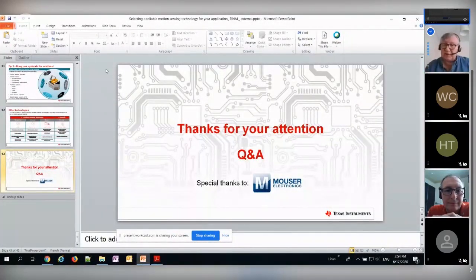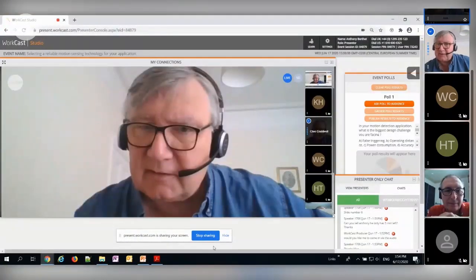But Paul Massey, quickly, from Saurian Electronics: is there a minimum distance that can be measured, and what are the limiting factors in that? Let me comment on that one. We are probably talking about the optical measurement. The distance that we are measuring is based on time of flight, so the distance you are measuring is the distance that the wave will travel from the source to the object and back.